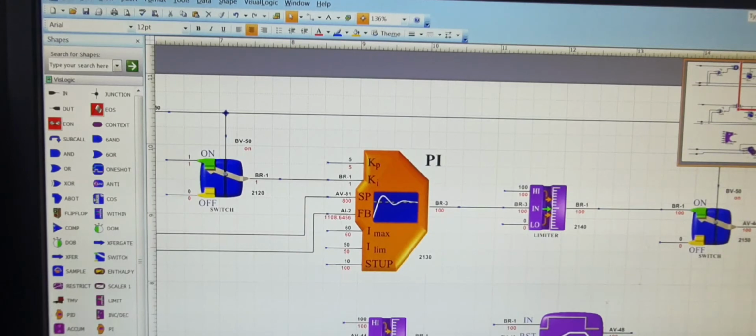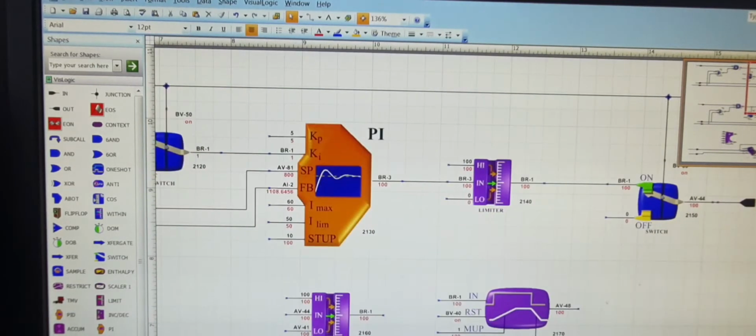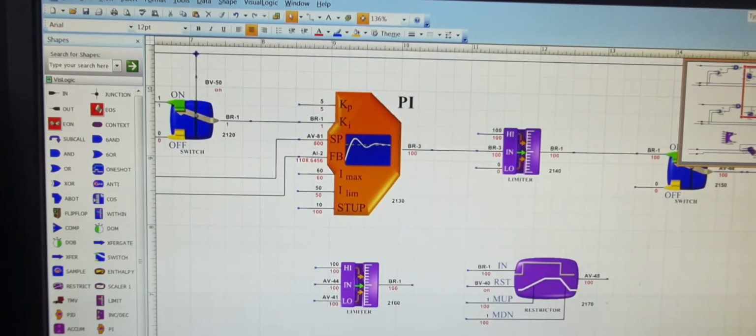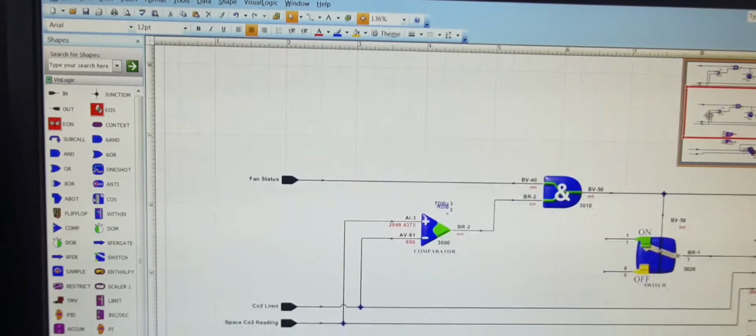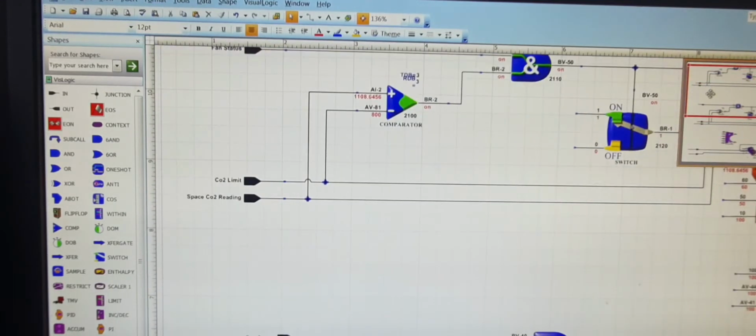Our first priority is health and safety based on ASHRAE conditions, regardless of if you're feeling cold or hot, because it's not life-threatening, or it doesn't affect your health that much. So we need to open the dampers fully and bring fresh air into that space. Okay. So again, this is another space we are looking at. I'm just going to show you a bit more of the programming side also here.